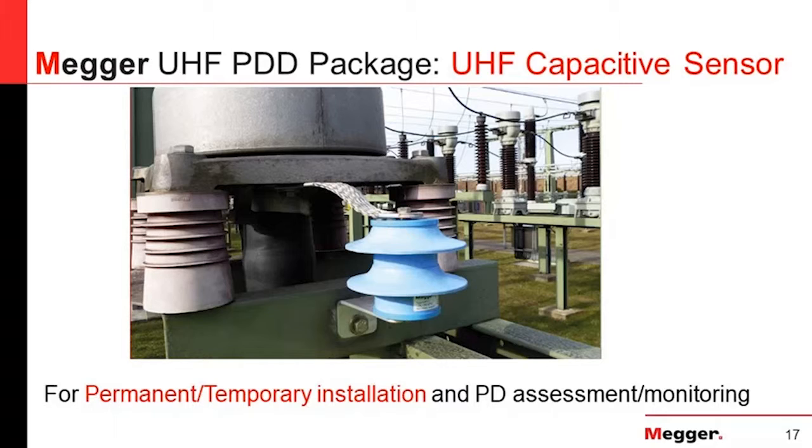And then once in a while, you can just connect your UHF PDD and check them one by one and see if something is wrong, and then save the image and compare the image and do the fingerprinting and things like that. This is UHF and it's very, very effective for internal partial discharge detection and can be used almost everywhere. It can be used temporarily or installed permanently.